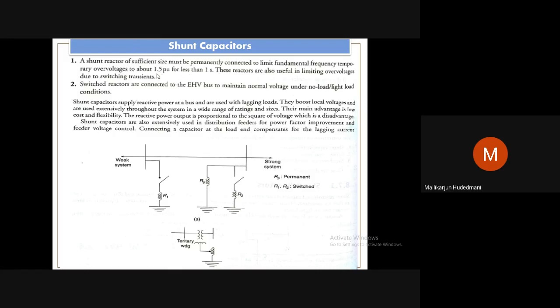That's what it means. You should be very careful to install reactors such that the overshoot of voltage over 1.5 pu and above shall not last more than 1 second. Within a second of observation, the overshoot has to come down very close to nominal voltage. In this regard, even the removal of the capacitor may not support. The addition of a reactor to absorb spontaneously along with the removal of the capacitor might work in coordination. So that's why series reactors are also important, as shunt reactors are also important like our shunt capacitors in this context.